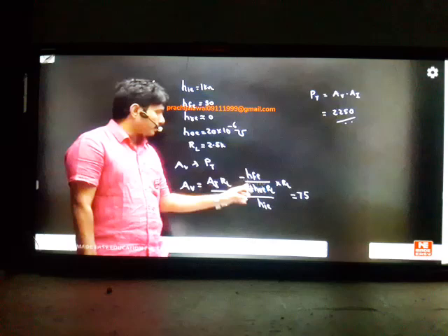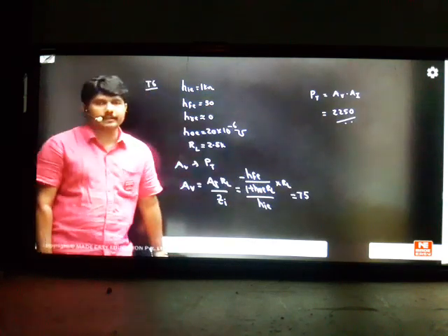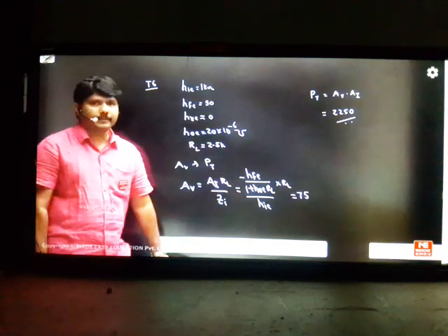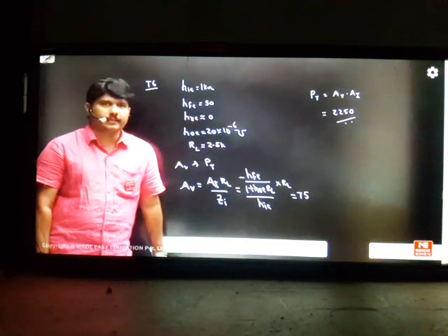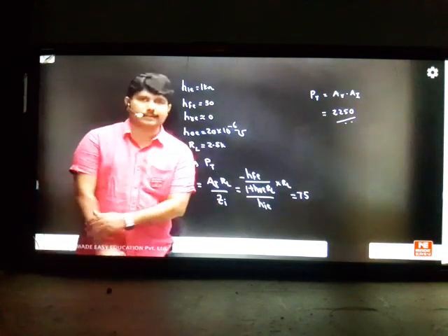Suresh Kumar, the total answer current gain is positive, but why is the negative sign kept? It is for voltage gain. For voltage gain we have a negative sign there. The minus is applied to make it a phase shift amplifier. Originally current gain is positive only, but the negative sign is an indication coming for the voltage gain analysis. So you have to write that minus, because it has to carry forward to the voltage gain in the calculation.